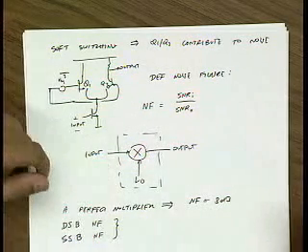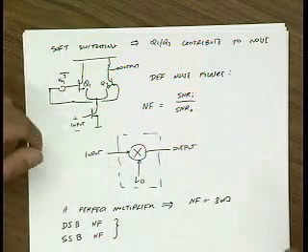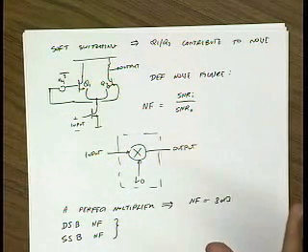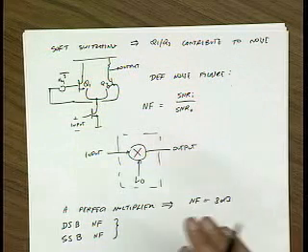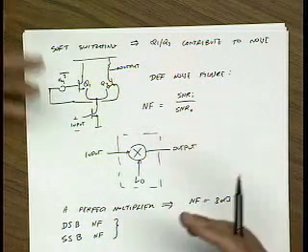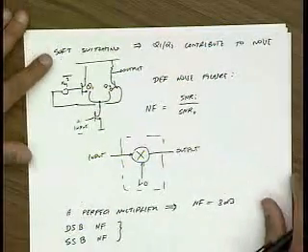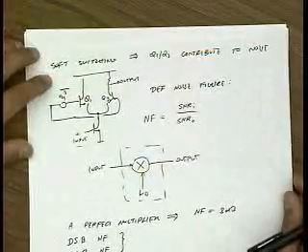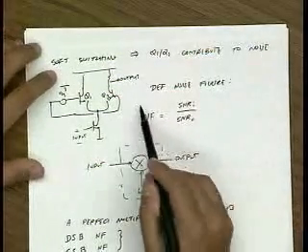Single sideband noise figure, on the other hand, assumes that there's only information on one band and noise on the other. So single sideband noise figure is either a minimum of 0 dB with the IEEE definition, or 3 dB with the non-IEEE definition, let's say. And unless stated otherwise, you can assume that this is the noise figure.